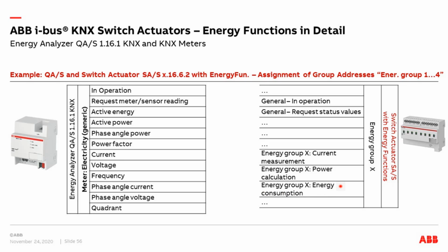So, and for the energy groups, it is similar. At first, we need 2 group addresses, if we use the in-operation monitoring, or to send here a read request, we need a group address. And again, for the current, power, energy, we need 3 more group addresses.